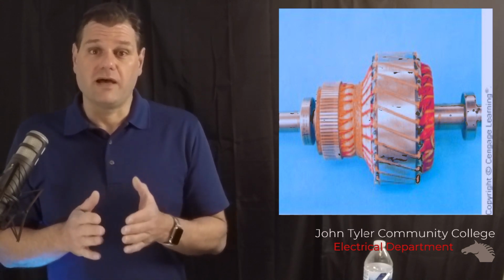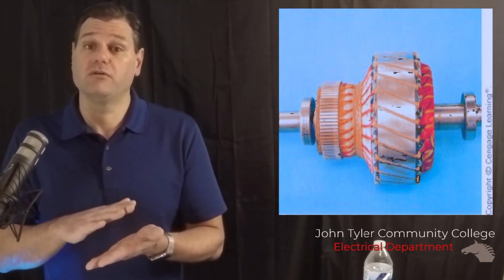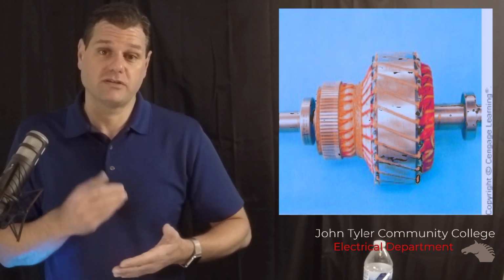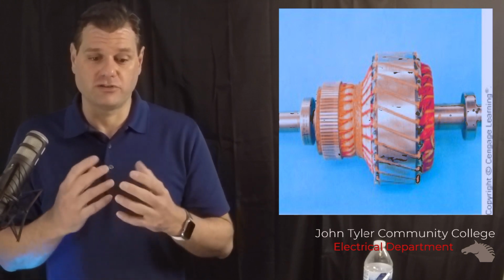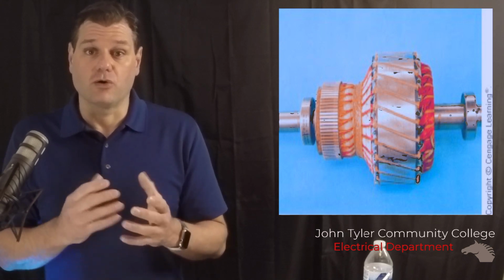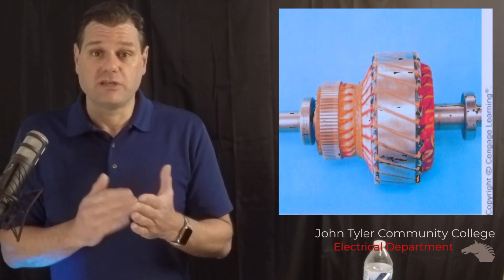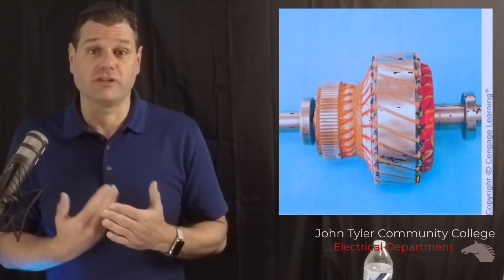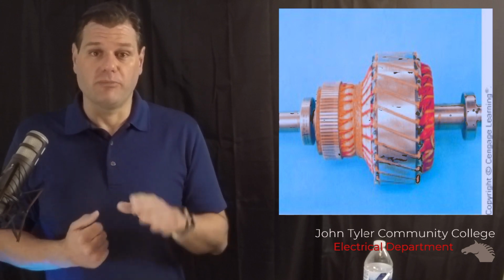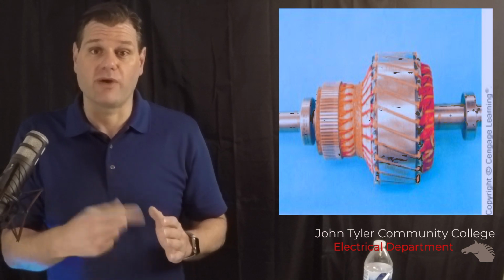That resin allows the wires to lay together without electrically making contact, so electrons cannot pass from one to the other easily. If you put too much voltage or current, you could possibly blow through that insulator. It happens. But typically, just a nominal voltage would not be able to go through, because they're not electrically connected. They're laying on top of each other, but because this one has insulator and this one has insulator, they're just kind of sandwiched. That's why you can get so many wraps.